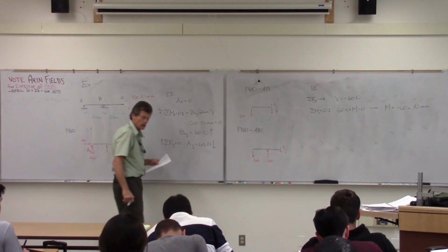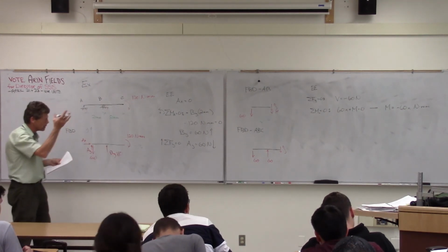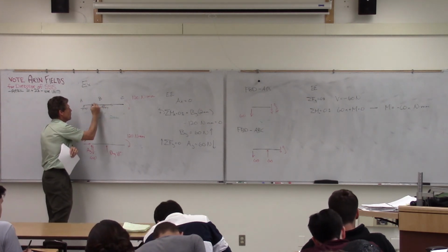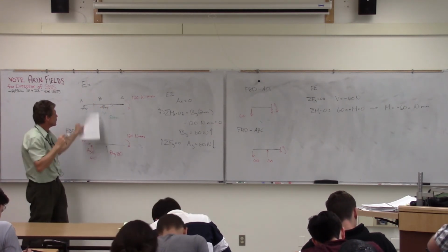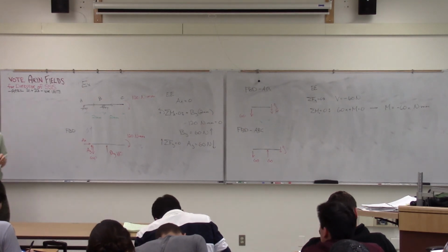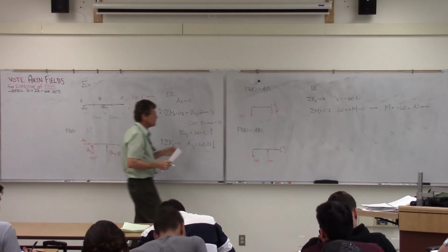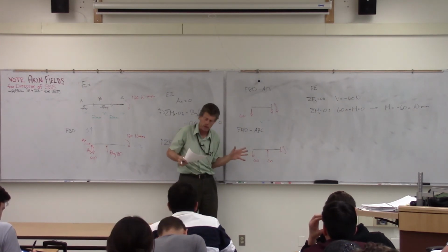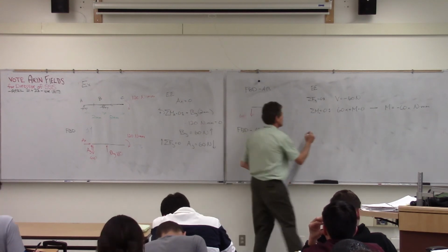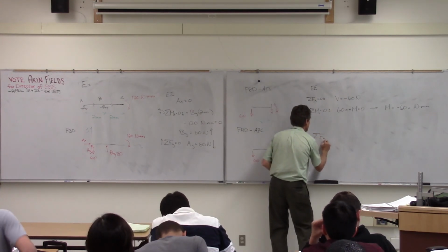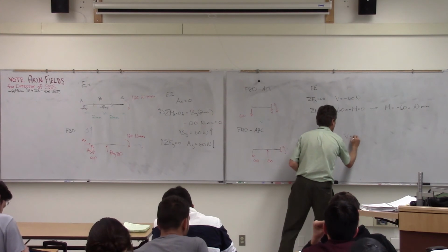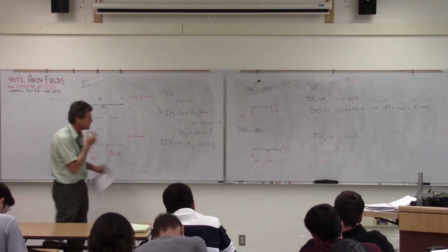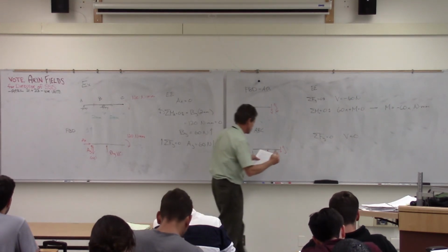Okay, so my free body diagram for the second piece there, the cut in this section, is now going past the support B. And the point I want to make here is now notice, don't think about it in terms of the support, but think about it in terms of that concentrated force. When I consider my equilibrium equation, B is now equal to 0. So I'm going to see a change in my moment diagram there, or in my shear diagram.